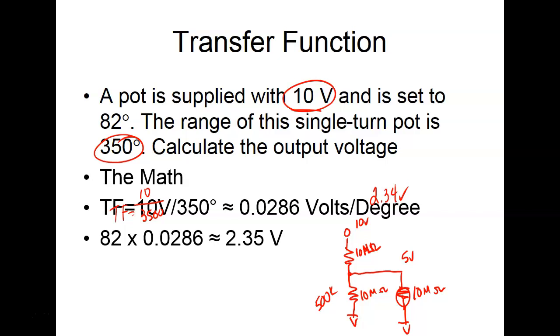So if I have a 10K pot, and my meter had 10K ohms of resistance, then all our calculations are out the window, because now I'm setting up a circuit like this. No matter what I do, I've got a resistor in parallel with this guy right here. So now all our calculations are off, because that's no longer just a pot, it's a pot that's actually loaded.